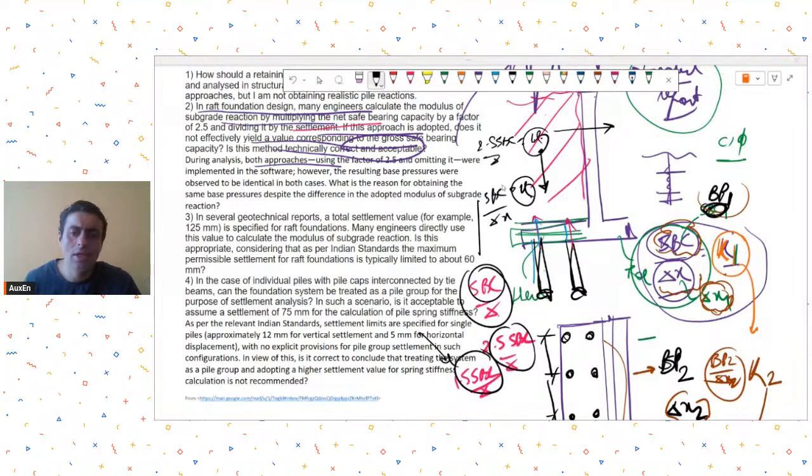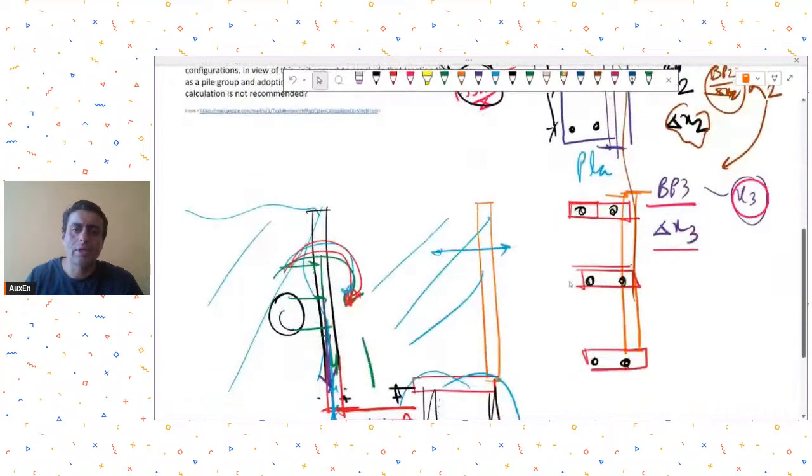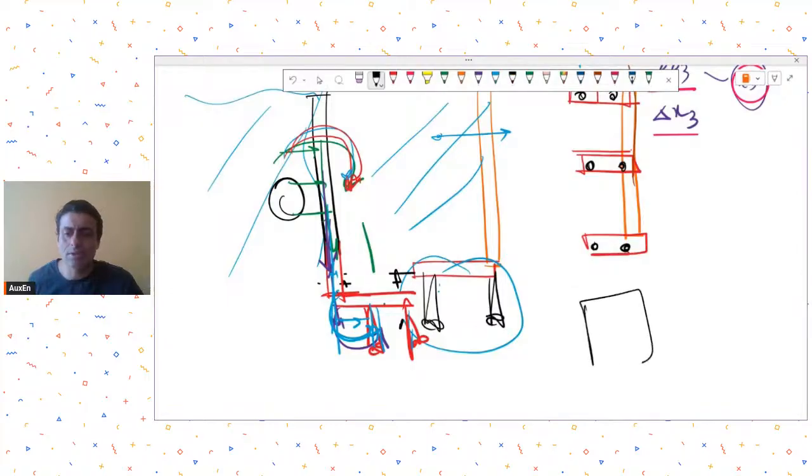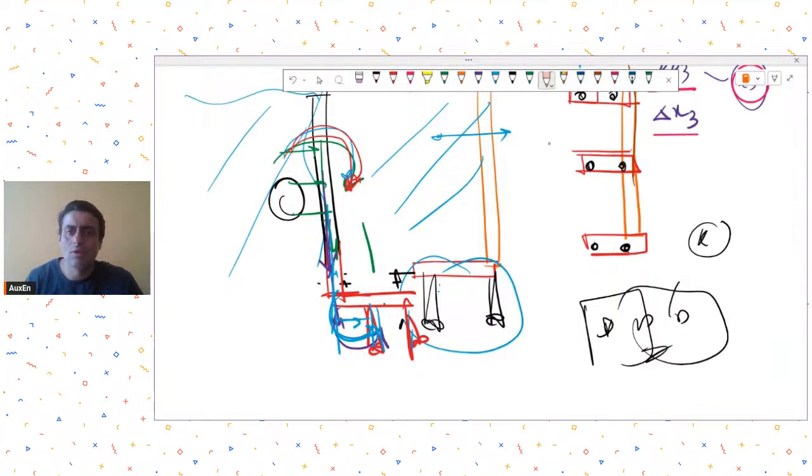Did you get it? This thing also happens with the geotechnical engineers. Ideally, what we should do is, once you are analyzing any foundation system, whatever raft, whatever, and your geotechnical consultant has given some K value, you take that K value, analyze your foundation system, find out the bearing pressure and settlement, and go back to your geotechnical consultant and tell them that this is the bearing pressure and settlement you are getting.